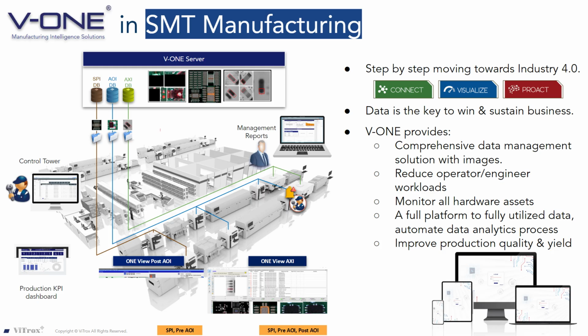So V1 provides a whole range of specialized dashboards. You've got your AXI, AOI, and SPSA dashboards, which stand for automated X-ray inspection, automated optical inspection, and automated solder paste inspection. These give you real-time insights into those inspection processes, and then you can see your production output, machine utilization, even process variation over time. Process variation is a big concern for manufacturers, understanding that can really make a difference in quality control.